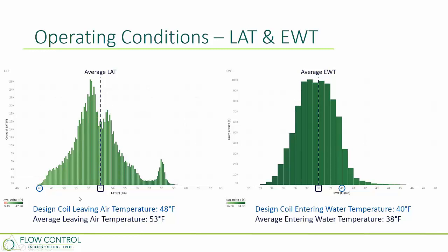And that goes into place generally based on code. Maybe it's a discharge air reset on outside air temperature. Maybe it's on a load. Maybe it's on a return air temperature. But that's very common across a lot of facilities.